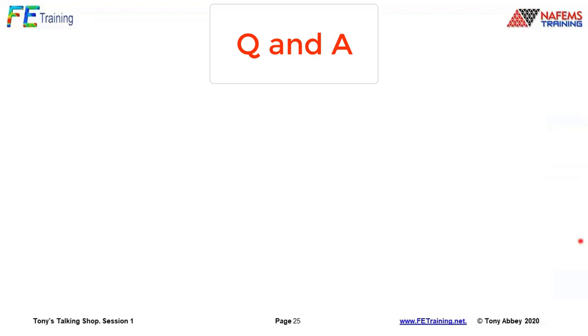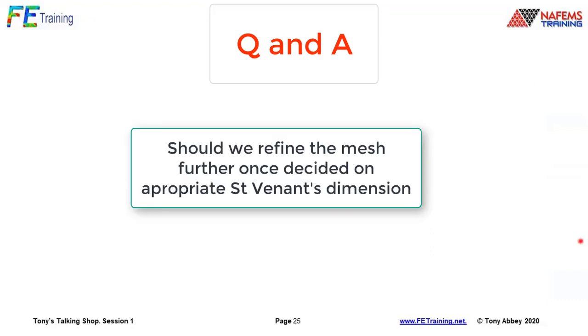Mike says, the fillet in your needle shaft or I-beam example, assuming the load was cyclic, do we use the peak reported stress or does mesh discretization cause an inappropriately high stress? Do we need to refine the mesh until we settle on a consistent stress? Yes, Mike, that would be a good second stage. So I guess the first stage would be to see if we got sufficient diffusion length, and we're really looking for the shorter the better. Then our local model is the leanest and meanest. Once we got to that stage, then we can throw elements at that.